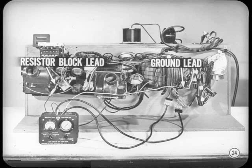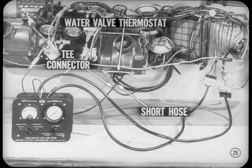Hook the clip to the terminal under the tan wire in the 3-terminal connector. The white lead goes to a solid ground. To make the vacuum connection to the tester, disconnect the control vacuum hose from the water valve thermostat and use the T and short hose to tap into the line.